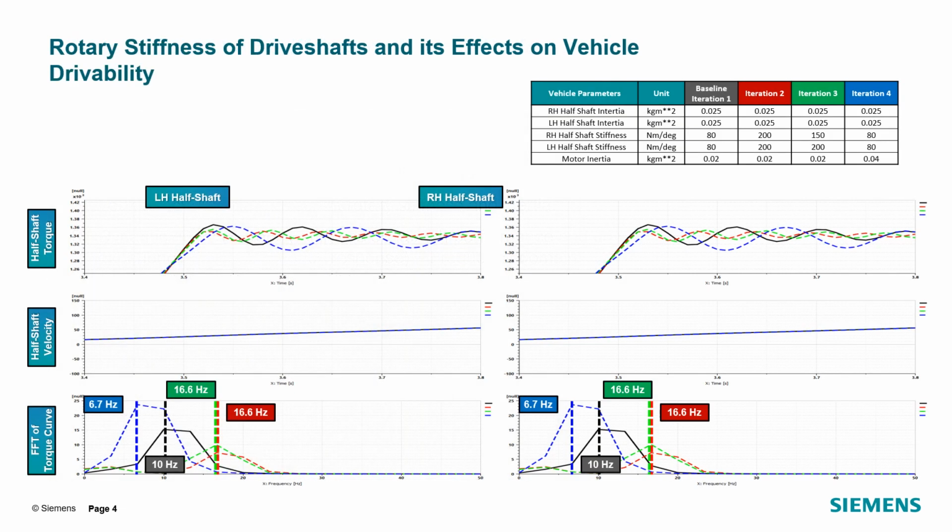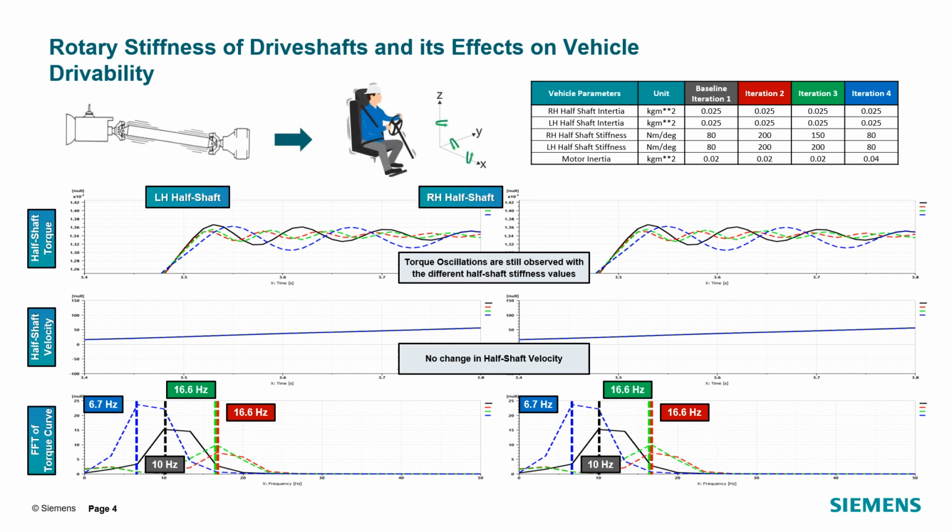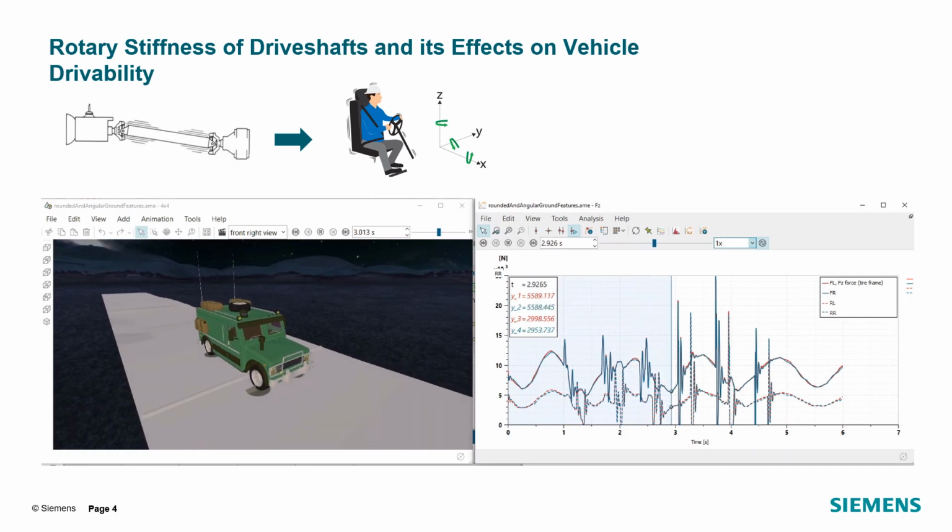As demonstrated in our previous chapter, half-shaft stiffness values can give rise to certain low-frequency vehicle shakes, especially during torque wind-up of the driveline. These resonances, coupled with other suspension resonances, can cause nuisance at the driver interface locations such as C-track and steering wheel, leading to poor drivability. Therefore, it becomes critical to tune the driveline systems, like drive shaft stiffness, to deliver a desired frequency range sensitivity, which can be evaluated and balanced with other vehicle attributes.